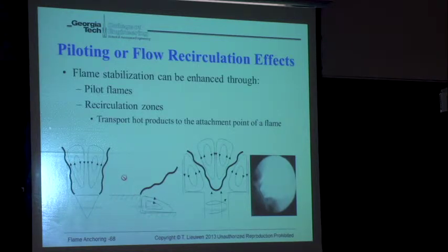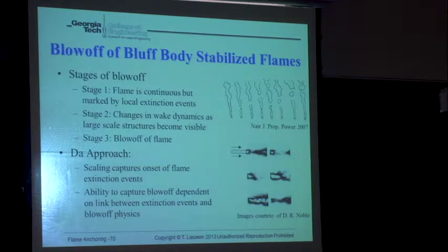Well, if you actually look at what flames look like as they start to blow off, blowout is really not a single event, it's really a process. So when we actually look at blowout, it looks totally different. Now that we have all these awesome high-speed cameras and high-speed diagnostics, life is just a whole lot more interesting than you might expect. So here, this is a paper we wrote in 2007 for a bluff body stabilized flame, close to blowout.